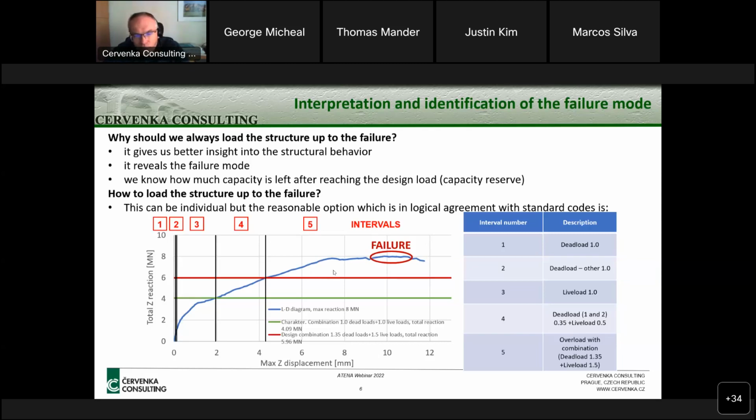So that was actually a good question because it reminded me that I should mention that in order to really calculate failure load, we cannot use the standard Newton-Raphson method in ATENA, but we should switch to the arc-length method. The arc-length method allows us to start decreasing the loads when we go to post-peak.